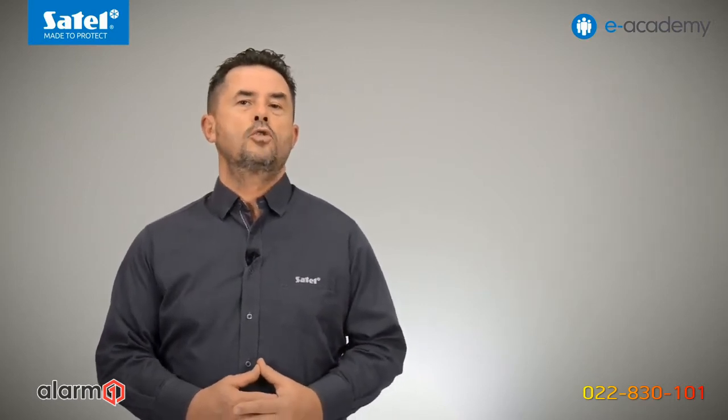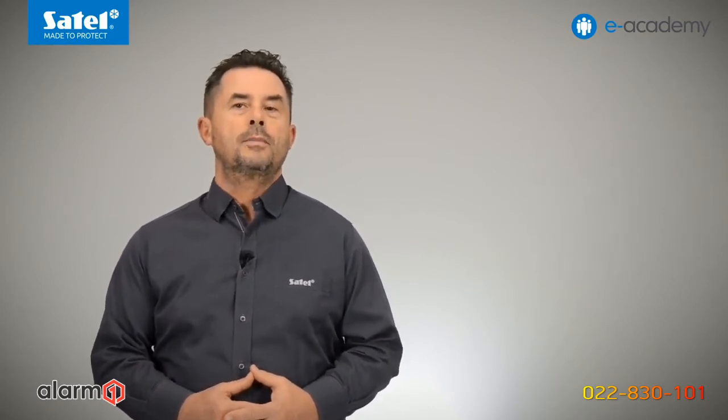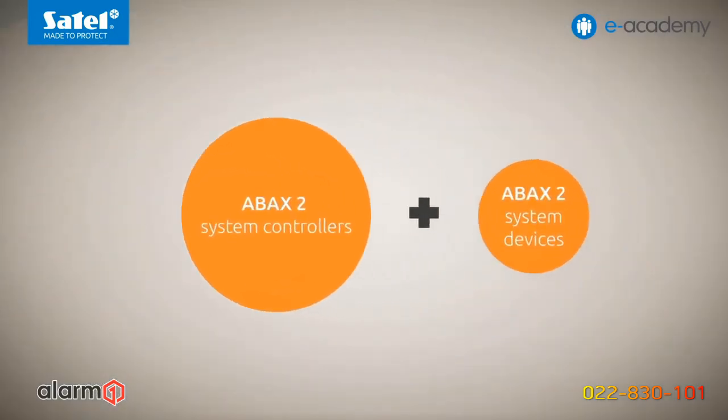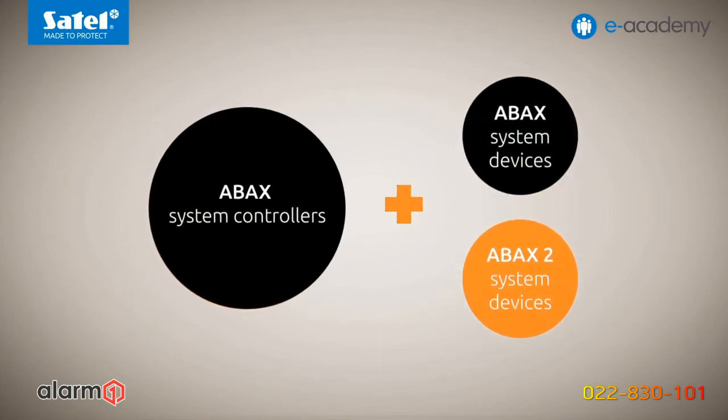Finally, a mention should be made of the compatibility of ABAX 2 and ABAX wireless system devices. Only devices of the ABAX 2 system can be enrolled into the ABAX 2 controllers, that is, ACU220 and ACU280. As for the ABAX system controllers, that is, ACU120 and ACU270, they can work both with the ABAX as well as the ABAX 2 system devices. However, in this case, the functionality of the ABAX 2 devices will be limited. For example, radio transmission will take place only on one channel of the 868 MHz frequency band. The range of such communication will also be much shorter.